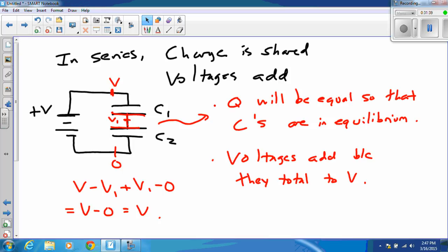Here I have a circuit lead that's just sort of jumping out to the middle of nowhere. See how that's not connected to anything on that end? That's just left over because I didn't feel like taking it out. This will actually have an undefined voltage at that point. Or if I connect it to something else, then it will have a voltage of zero, the same as the negative power bus.